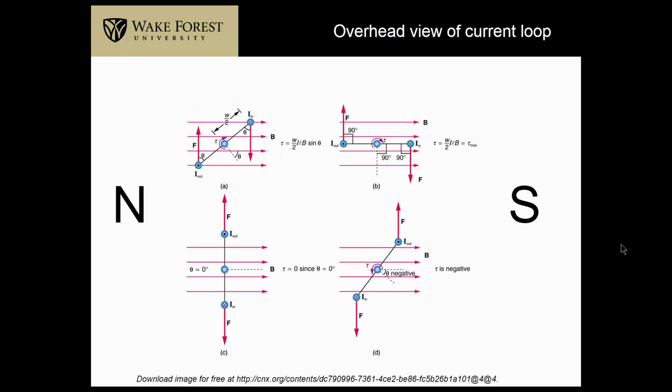We would continue to have a clockwise torque, spinning the loop under the power of that current that we're driving through the loop. This is, in fact, a motor. We just made a motor by reversing the direction of the current at just the right moment when the loop passes vertical, as seen from above.